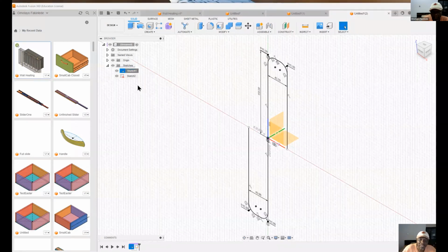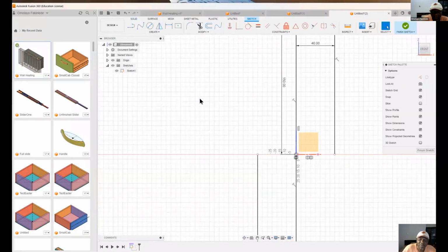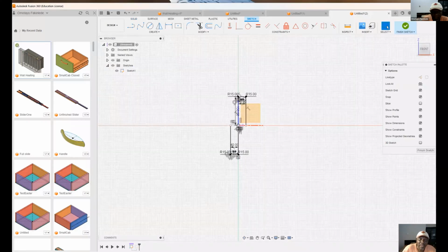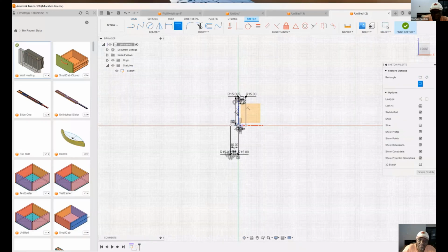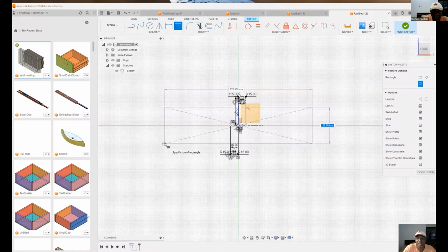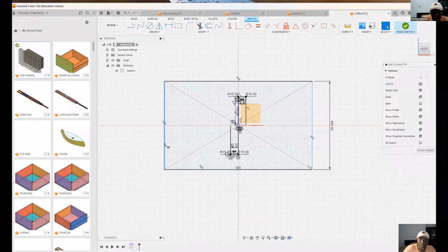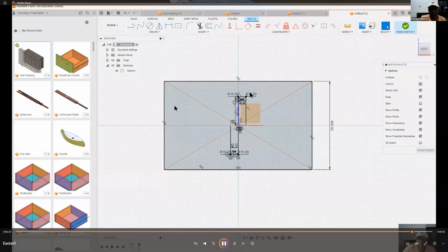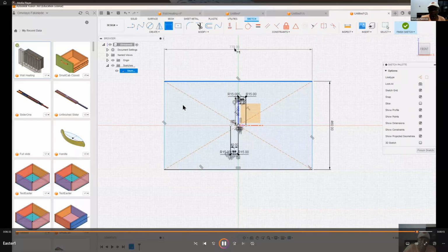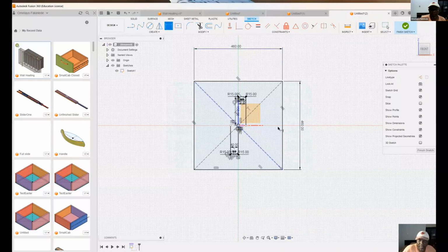If we choose edit sketch, then we can now make it smaller here, and then take a center rectangle from the middle here, and let us say the length there is, let us make it 460, and the breadth, okay, no, that's not what I want. Okay, we can redo that by using dimension. Okay, so let this be 460, and let the